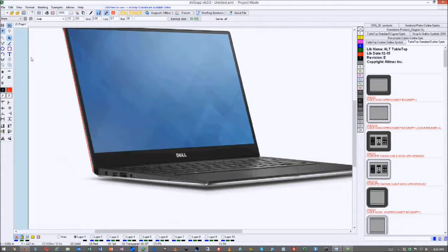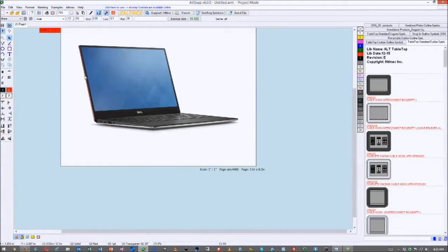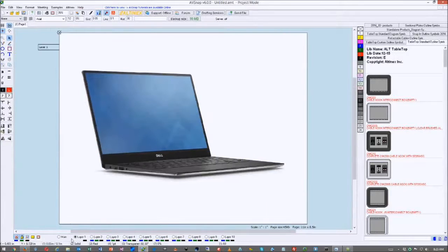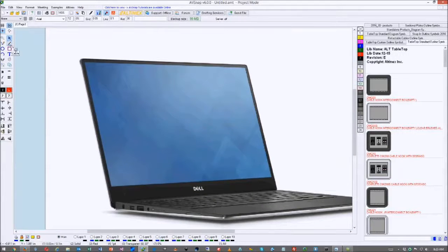So I'm going to go ahead and select the layer. Make sure before you start drawing the line, go to the main layer right here on the bottom left corner. So let's go ahead and draw the line, and you can see if I draw the line, then I have to later select the line again. So I want it to be a little bit more automatic. So what we're going to do is click here, and then press the tab key. The tab key will change the icon. You can see the icon change with automatic. It's called the gluing mode, okay, where the lines are glued together.